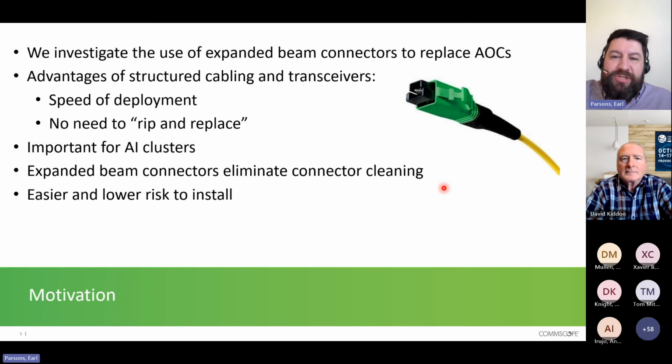But the way these connectors are designed, you see the ferrule is right there in the middle. We've got this kind of protective housing around it. These also had anti-reflection coatings. So even if you had something causing a gap, you wouldn't have bad return loss like we see with PC multimode MPO sometimes, where we lose physical contact.